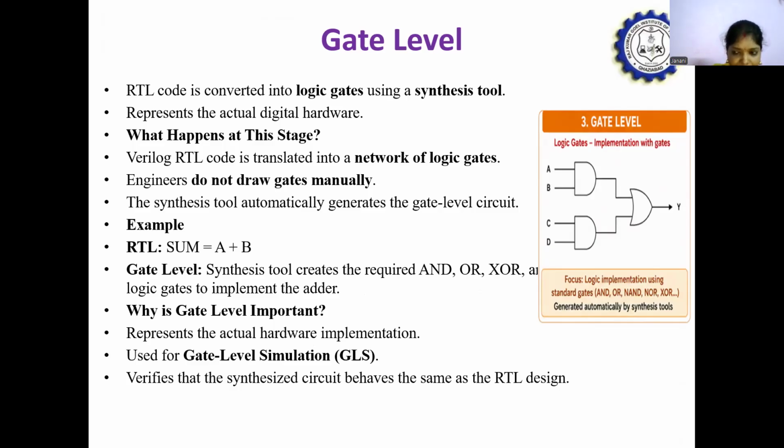In the architecture level, as I said earlier, we just decide that we need an adder block. In the RTL, we describe the function of the block using Verilog code. We write sum is equal to A plus B. In the gate level, this code is converted into the actual logic gates.